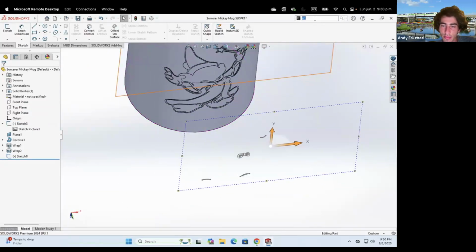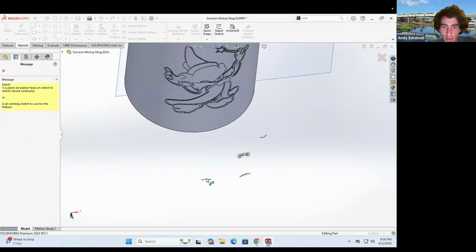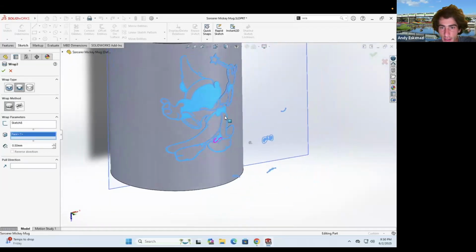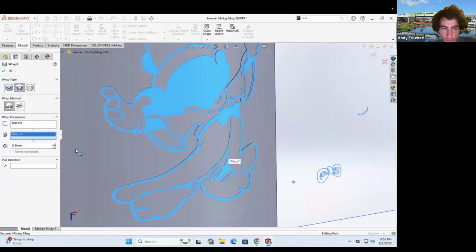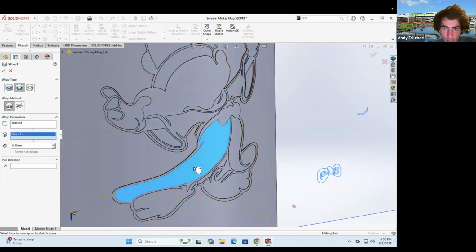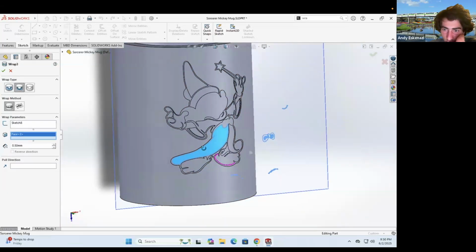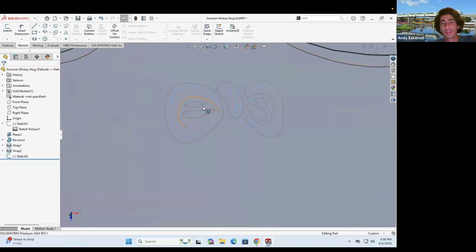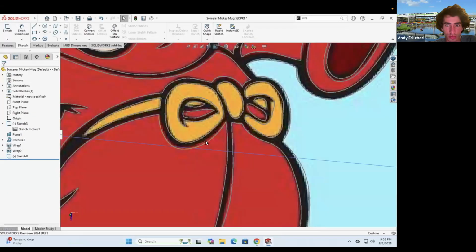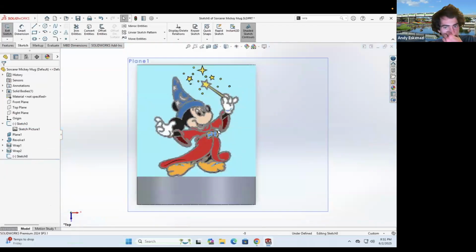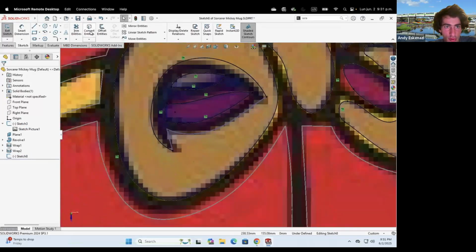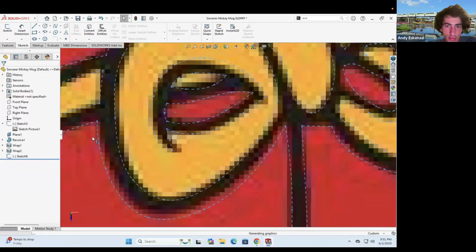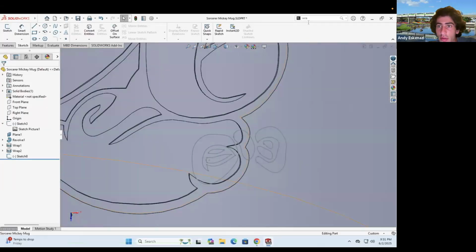And now let's go here to wrap. We're gonna select this face. It's gonna be this. And let's see. Actually, it might not be that face, might be here. Just thinking for a moment. Oh, I see what's going on. I forgot, it's not closed. I need to show this again, edit the sketch, and add convert entities, that and that. Otherwise, yes, this is for sure not gonna work. Actually, now it might.